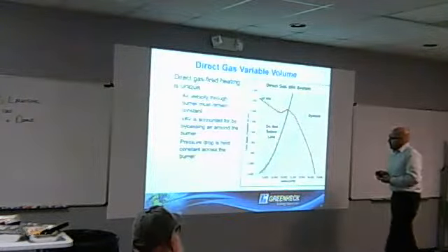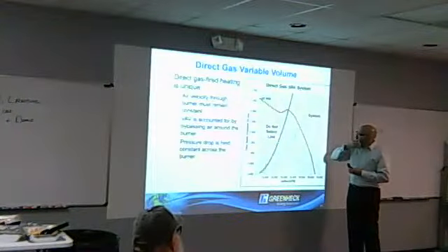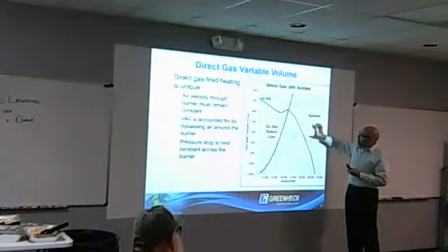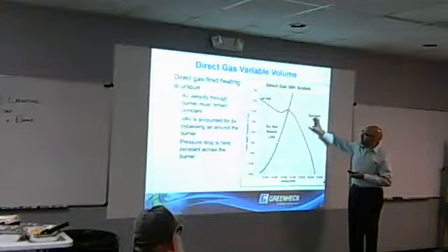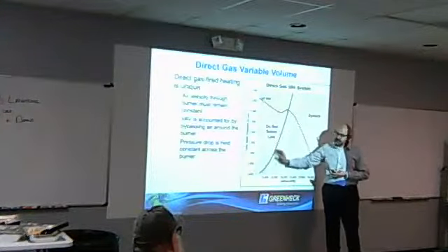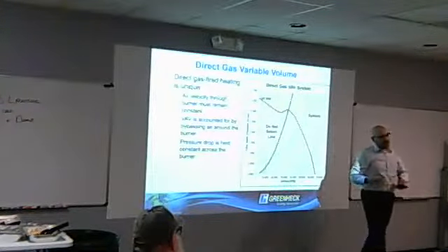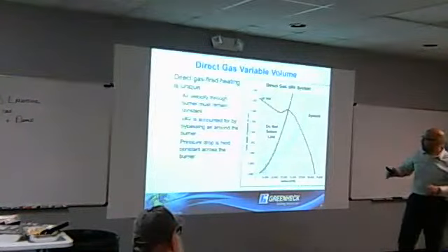This is to show that you could vary the burner, but the performance of the air is going to be a function of the pressure drop over the burner, but also the fan. If you look at a fan curve, there's always a line that you do not select to the left of. Some people call it the surge line or the do not operate line.